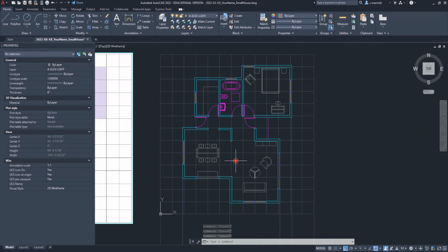Basically, what you want to do is choose a spot somewhere in the project to cut your section. So it could be anywhere. I could make my section cut here, and then I'm going to show everything that I would see past that section line. Everything behind the section, this front part, would not be in my drawing.